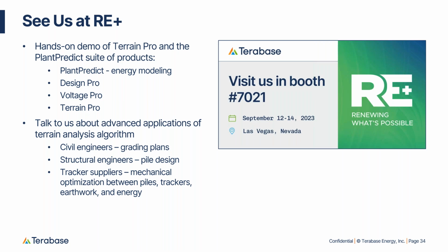East-west slope is currently not one of our design parameters, but this can be modeled with the results that come out of Terrain Pro. You can get finished grade elevations, top of pile elevations, and then you can model those to visualize the east-west slopes. In my humble experience, I've found that if east-west slopes are too steep for the tracker, they're too steep to even build on. So that's my experience. But yes, you can model that with the data you get out of Terrain Pro.